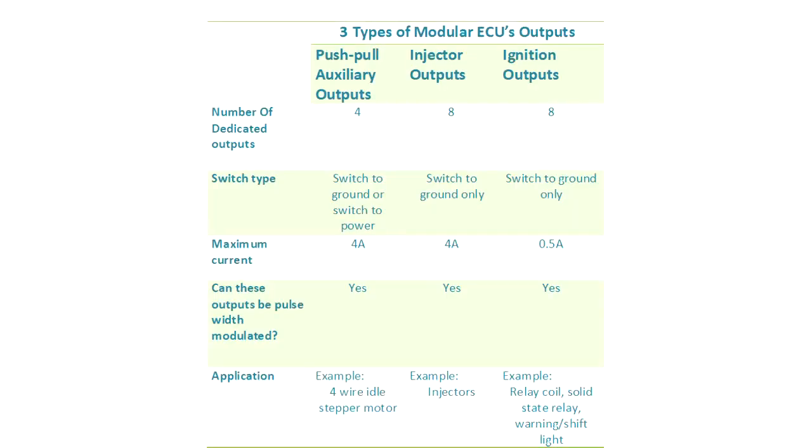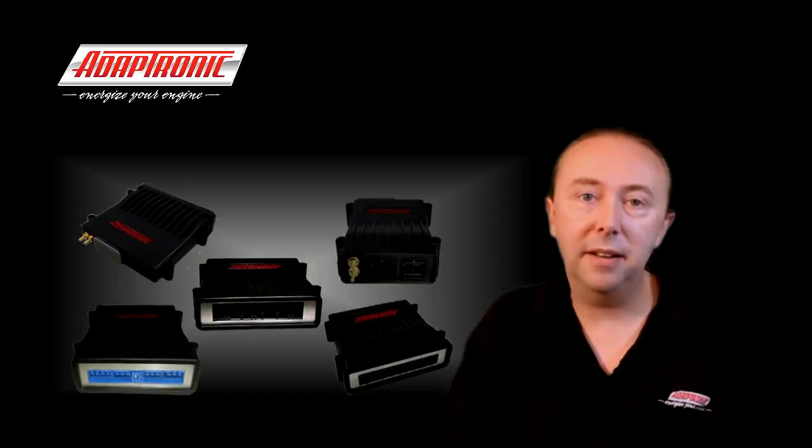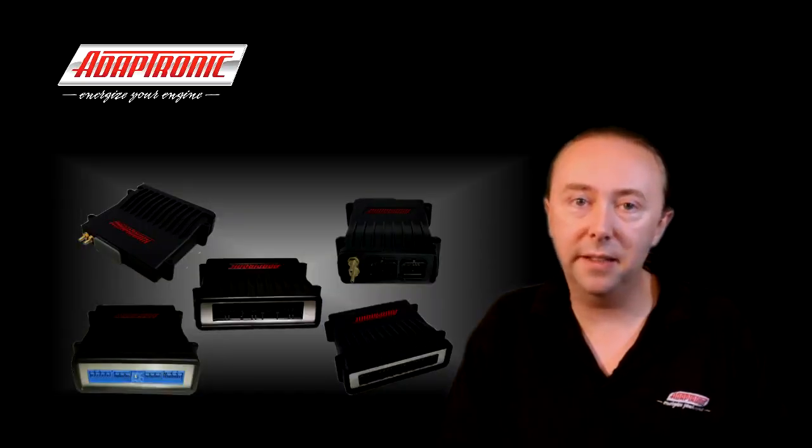The second is an injector output, which can also be used as an auxiliary output. These can only switch to ground. The maximum current that we allow is 4 amps, which is the same as the auxiliary output. And these can also be pulse width modulated.